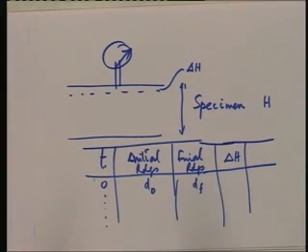Now, how and when do we know that we have to take the final dial gauge reading? Normally what happens is, when you apply a stress, the compression phenomenon starts taking place. This compression phenomenon, as we have seen, is time dependent, and that is the reason why we are looking into this phenomenon so critically. And it, theoretically speaking, goes on taking place indefinitely. But then from a practical point of view, the dial gauge reading, which in fact depicts the compression, becomes steady after a certain period of time.